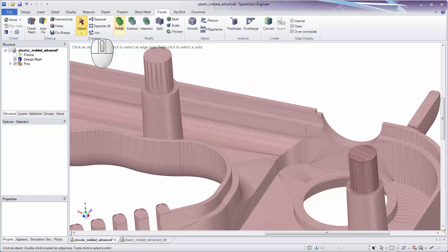And if at any time merge or subtract doesn't work with a solid and a mesh, try changing the convert parameters or options to be a little more coarse and less fine, so higher values.